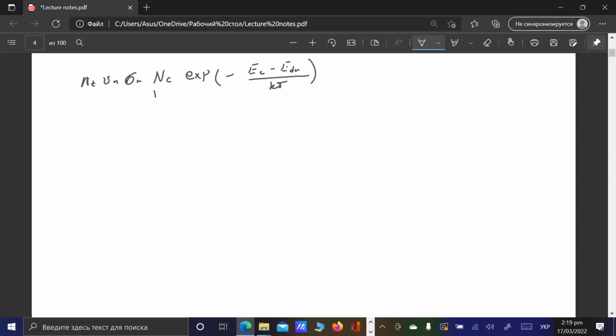So this guy stands for N1, but we assume here, instead of trap energy level, this demarcation energy level, for which probability of detrapping of electron and catching a hole from the valence band will be the same. So here we put actually the probability of this energy level to trap a hole from the valence band.